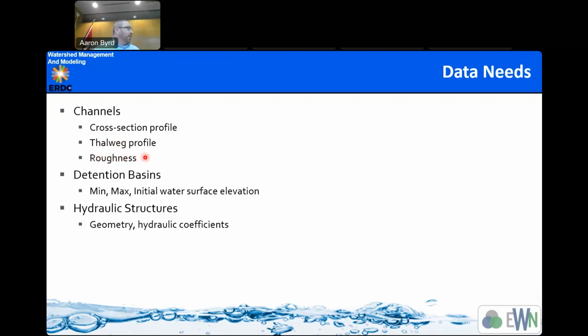And the channel roughness. So you need a channel roughness. This is the Manning's roughness. While you're driving around, you can ask, what's on the bottom here? Take some pictures, pull up your little chart of different roughness values for channels and go, okay, this makes roughly this or that or the other. Use those as a good starting point for your calibrations.